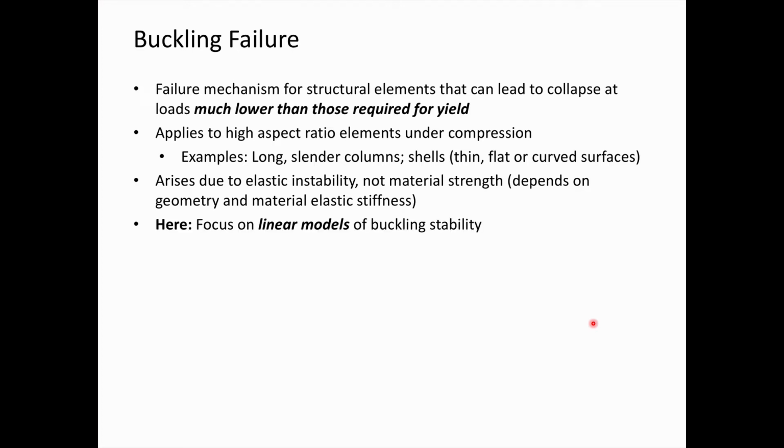Right now, we're going to focus on linear models of buckling stability. These allow for some easier analysis and also really important insights. But there are some limitations because there are big assumptions that are required for us to proceed with these linear models. We're going to derive ordinary differential equations, linear ODEs, to figure out what are the critical loads where elastic instability can occur. I hope you've seen this in previous courses.